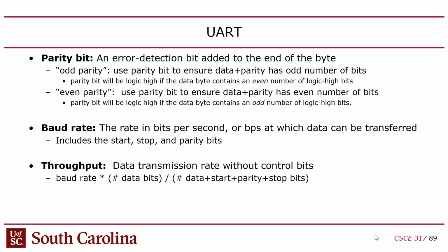I know you can set up more than one stop bit. I don't know if you can set it up with more than one start bit. But there are some options that change the overhead in terms of the number of bits that are not data bits, right? So there's 8 data bits, but there can be 2 or more miscellaneous bits that are used for framing.